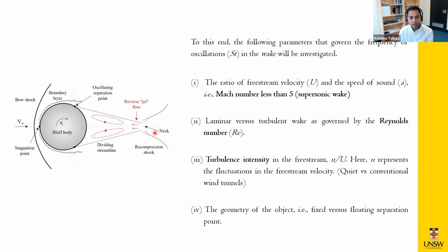So we are going to look at some of the key parameters we think affect the wake oscillations. We think the free stream turbulence within your tunnel or in your simulations could be affecting your wake oscillations. There's a common theme called the receptivity problem in hypersonic flows: how the disturbances are processed by these shocks, and how they affect the flow development downstream. There is also the Reynolds number effect, whether the boundary layer is laminar at the point of separation, or turbulent at the time it separates.